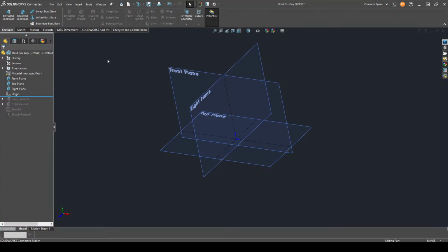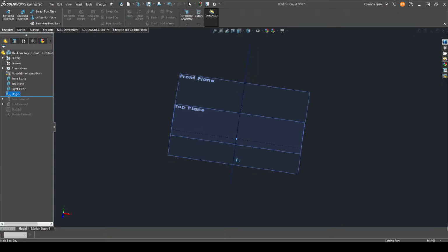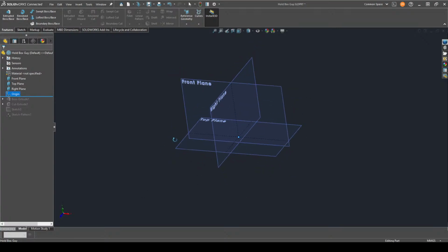One of them that I spent a lot of time with is Creo, and it just flips the coordinates. But regardless, these are just telling you, here are your 3 basic planes in 3 different directions for 3D space, right? And that's just your building blocks for starting it off. And then you have your origin here, which is the 0, 0, 0 of your model. For any software that'll read in this model, this will be the center of that part in particular.